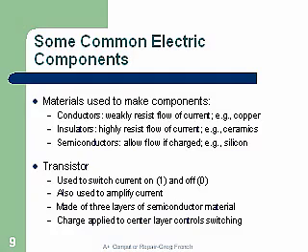Transistor, used to switch current. That's where we get our 1 or our 0 for our on and off states, our binary logic. Also used to amplify current. We can use them to amplify. Made of 3 layers of semiconductor material. Charge is applied to the center layer, which controls the switching.